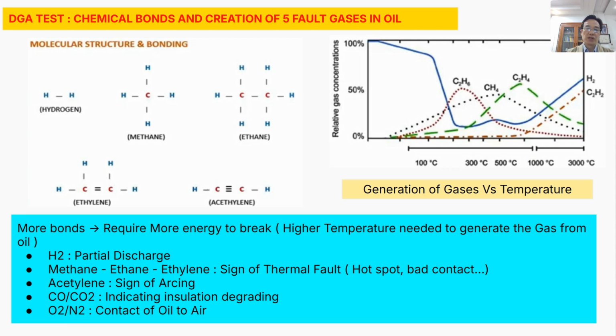In conclusion, we can say the faults in the transformer will generate gas inside the oil. Then based on the content of the gases dissolved in the oil, we can understand what fault now exists and what fault is developing in the transformer. Of course, there are some very special situations. For example, hydrogen sometimes may not come from a fault.